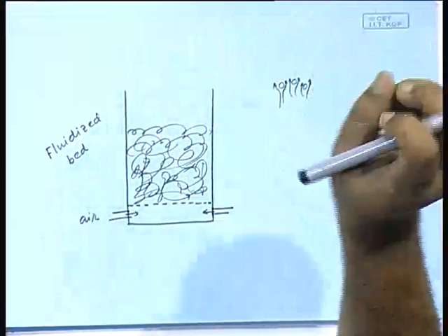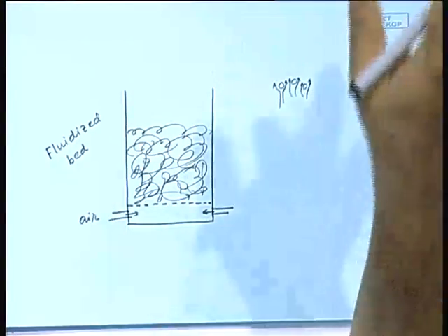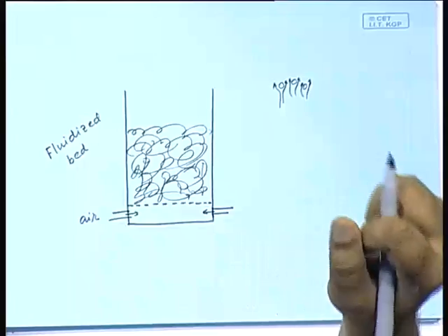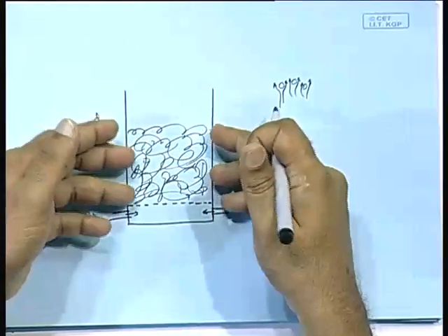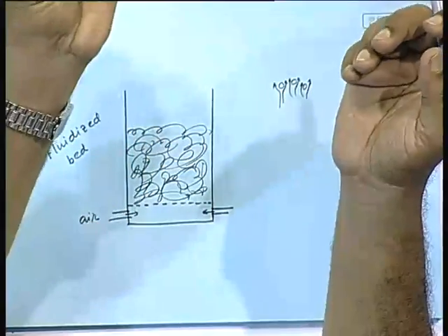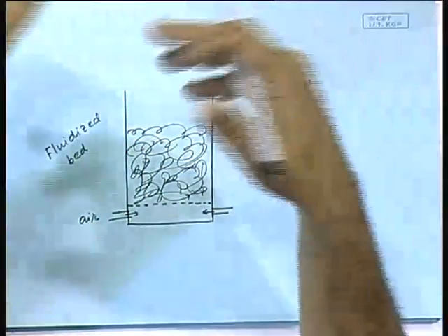The second advantage is that since it is not pulverized, the flue gas does not contain all that much ash. So it is easily taken out. The suspended particulate matter problem can be almost eliminated. All these can be taken out from the bottom as chunks of ash, which can be much easily handled.